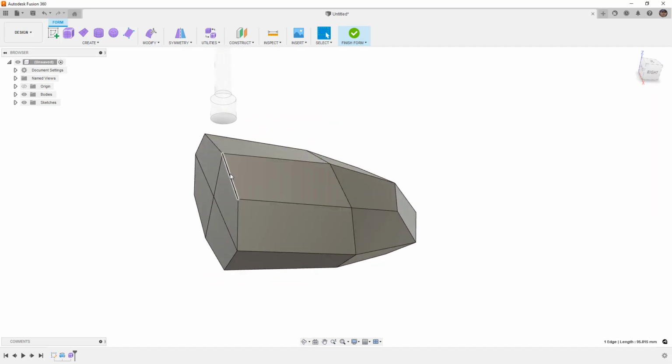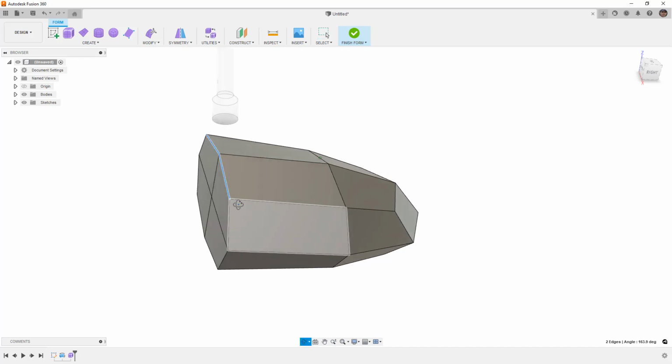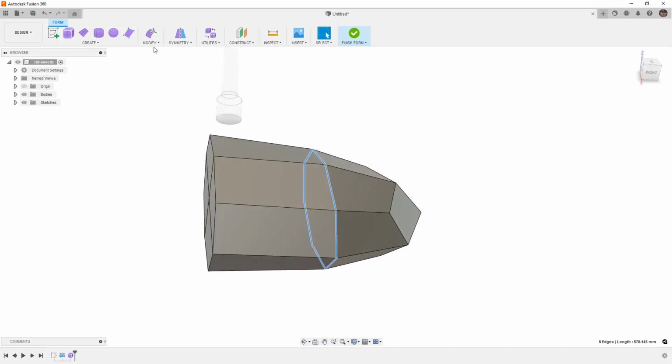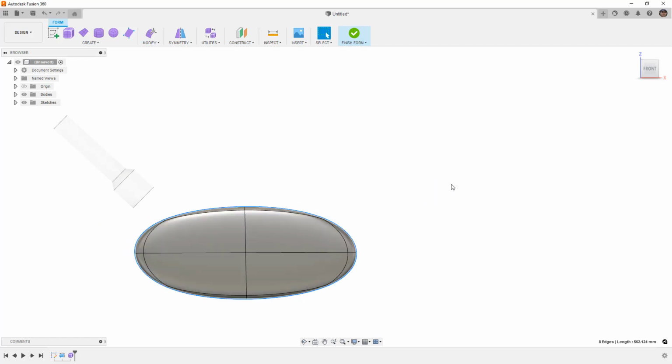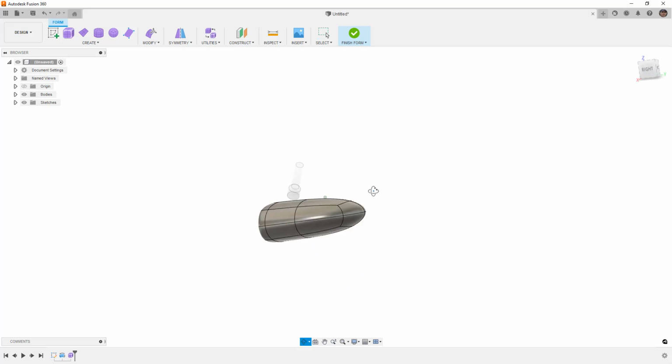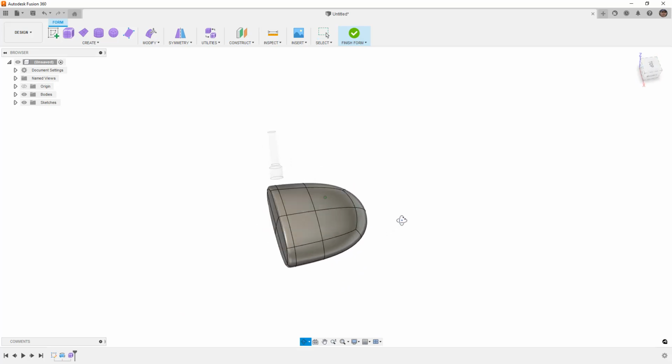If you want to play around with it, we're not going to end up with a crease, but what we're going to do is take insert edge and pull it really close to this one here, and then we're going to scale this up. Now, this is probably not something that's going to stay just yet, but we're going to scale it up just a little bit. I'm going to go 1.01 and hit enter. And if I go to smooth display, now you can see that we've driven the face of the club to be a little bit more flat.